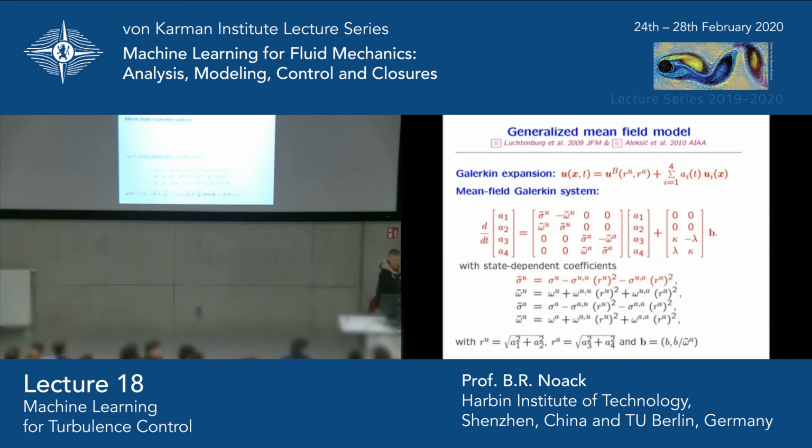And what this equation tells you is that you excite one frequency, it changes the base flow, and by changing the base flow, it mitigates the linear system of the vortex shedding. This is an example of frequency crosstalk, which you would miss with any linearized approach. Any questions so far?